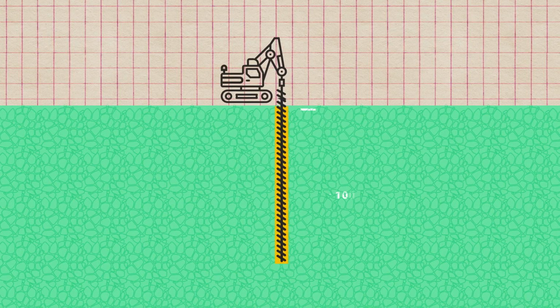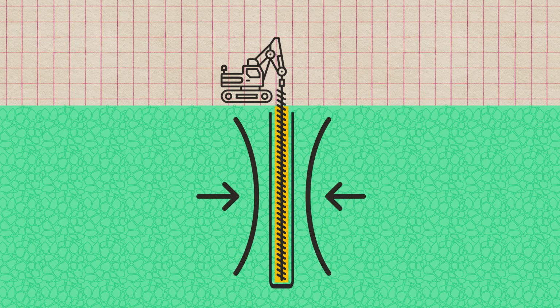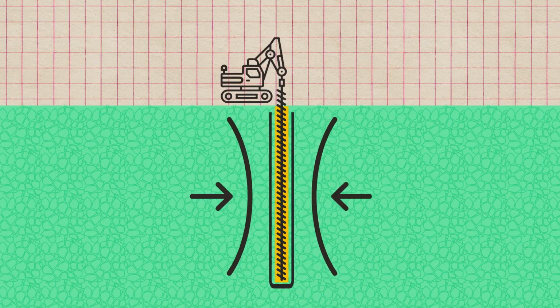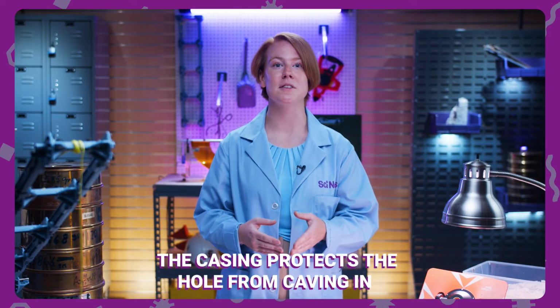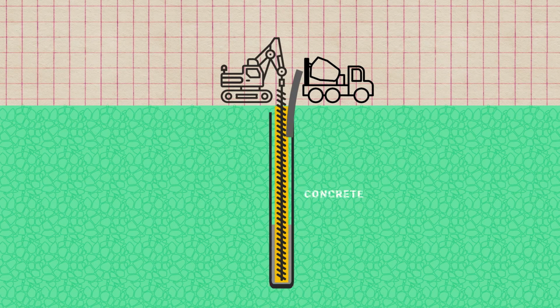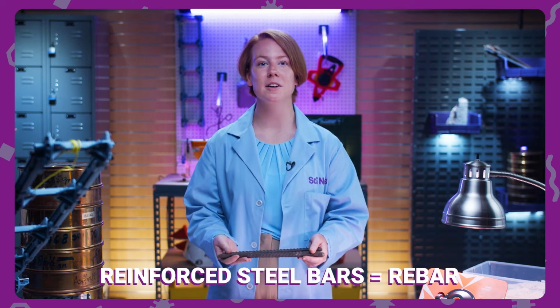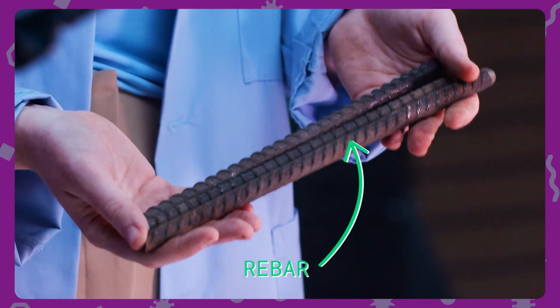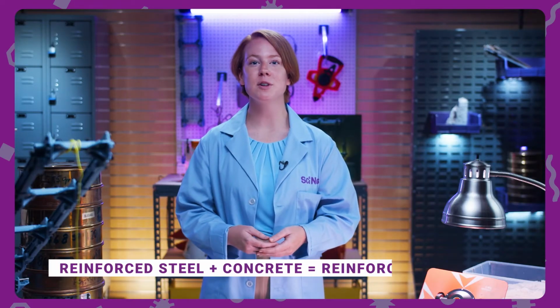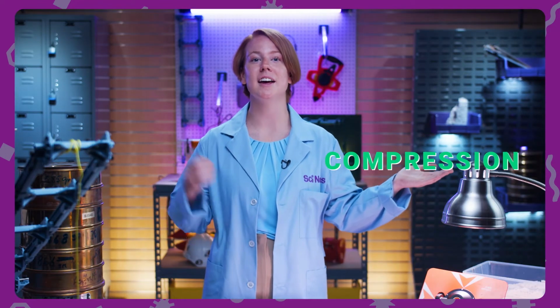The augers used for construction, however, can be driven 100 feet deep. A casing is also driven down into the ground so that additional soil doesn't cave into the hole that the auger is drilling. It's important that the soil retains its structure while the auger is in use. Once the hole is dug, concrete is poured into the hole. If additional strength is required, groups of reinforced steel bars, or rebar, can be placed in the hole prior to the concrete being poured. This is an example of rebar. The combination of reinforced steel and concrete is called reinforced concrete. It's commonly used for foundations and structures that undergo both compression and tension.